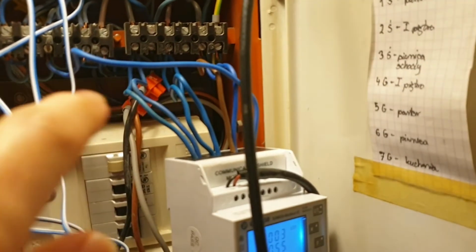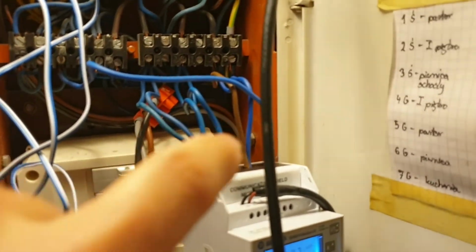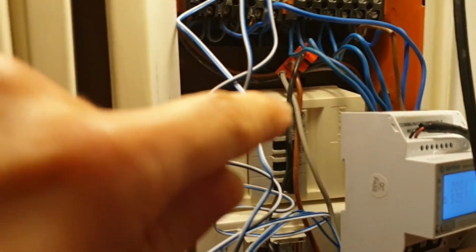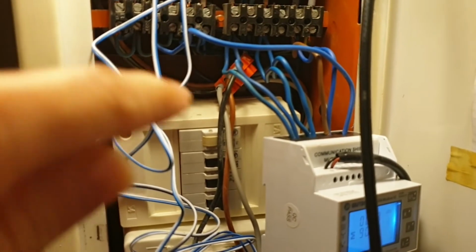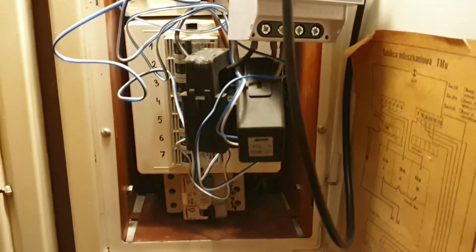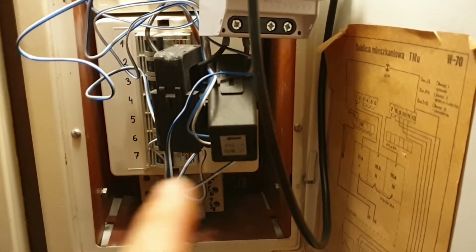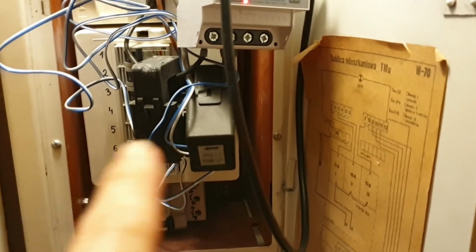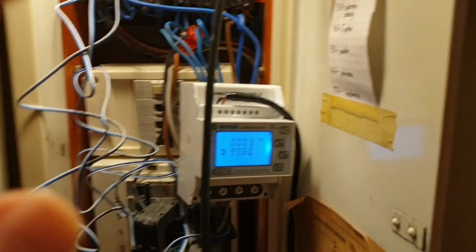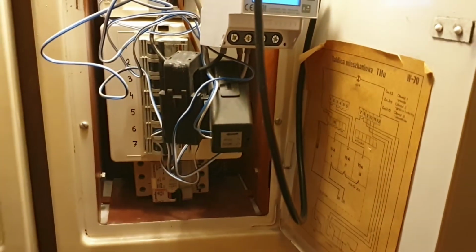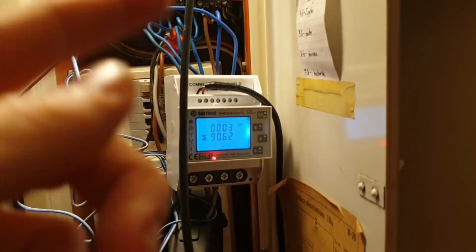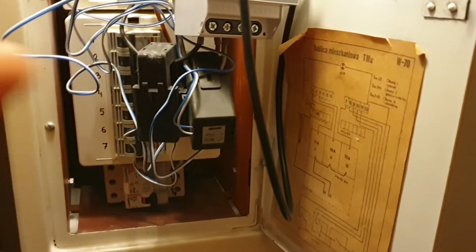At the top you can see also the cables which are connected on the right of the main fuses box. So those cables are the output from my inverter, and also you can see that extension here for all 3 L wires, which is needed to use that Huawei power meter, because it works like a transformer, as you can see here. So it doesn't need to be connected on each wire. It works the other way. So the Eastron power meter needs to be connected and the Huawei doesn't.